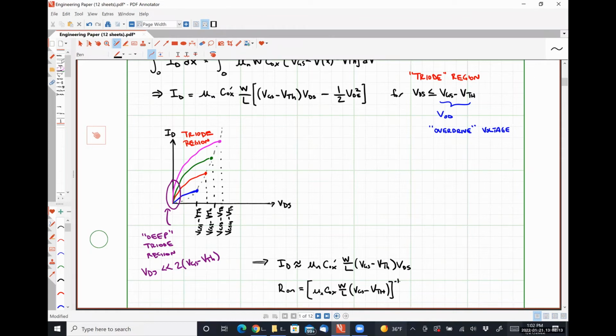So when we're dealing with resistors and resistances in integrated circuits, we're typically dealing with what's called a sheet resistance. So what that means is that if I have a square, it does not literally matter what its physical dimensions are, but if it is a square of material, it has a particular resistance. So if I have one square that is 800 ohms, two squares becomes 1600 ohms, etc.